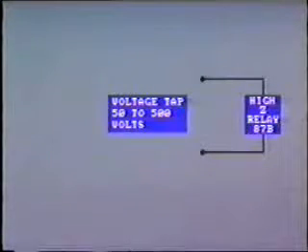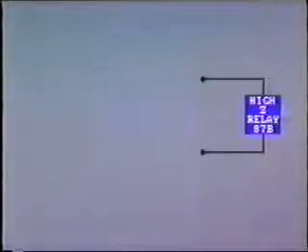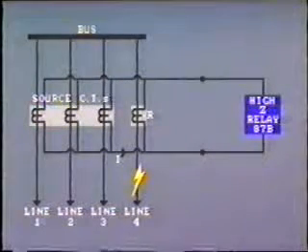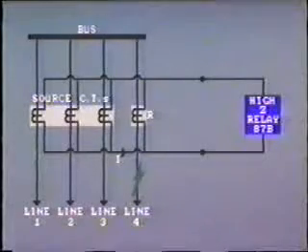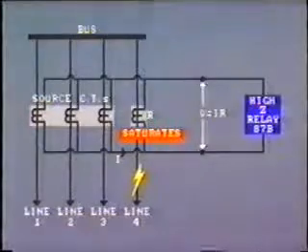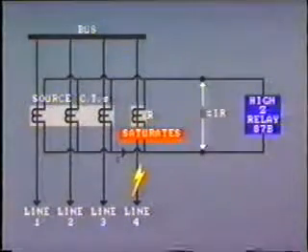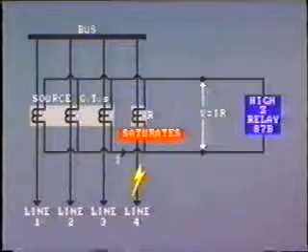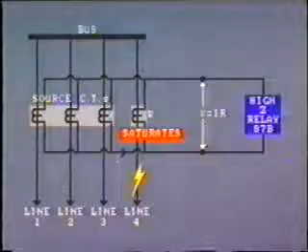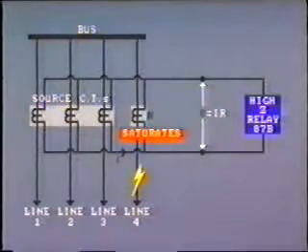The setting of the high-impedance relay is achieved by selecting the correct voltage tap, usually between 50 volts up to 500 volts. Let's look at an example to see how the relay's pickup value is determined. For an external fault, the CT in the faulted line may saturate. A voltage, which is the product of the current from the source CTs times the resistance of the windings and leads of the saturated CT, will be developed across the bus differential relay.